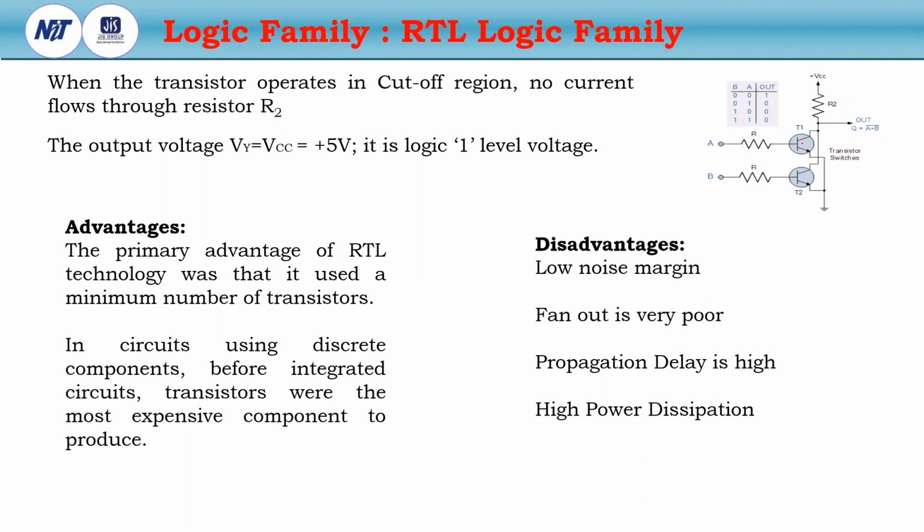Now if both these transistors are in cutoff mode, then there is no path from VCC to ground, so no current will be produced. For this reason, the output is simply VCC, logic 1. So this is the basic operation of the RTL.